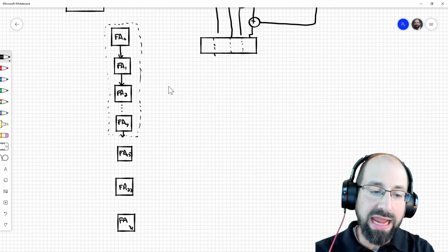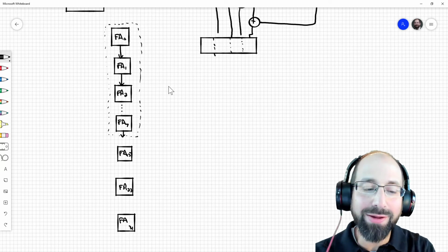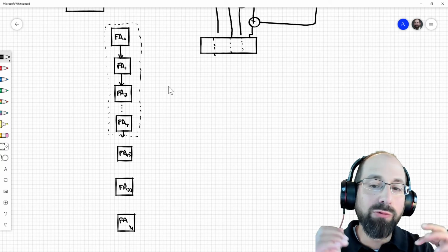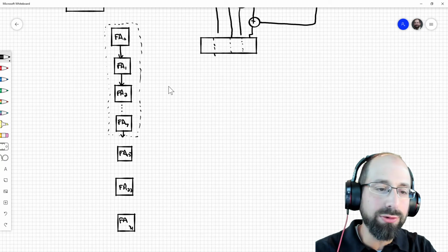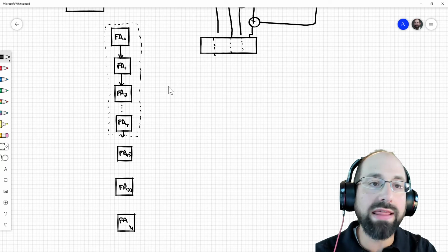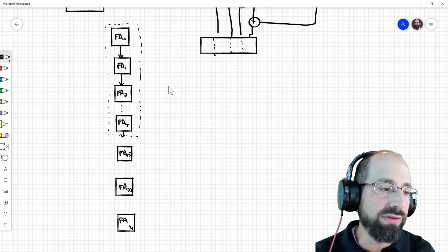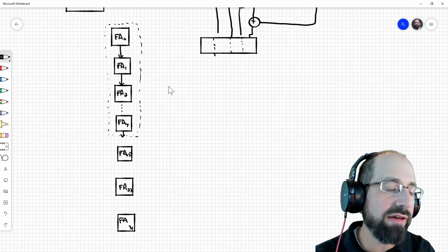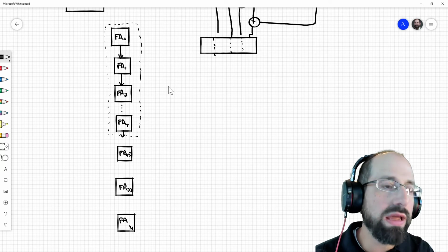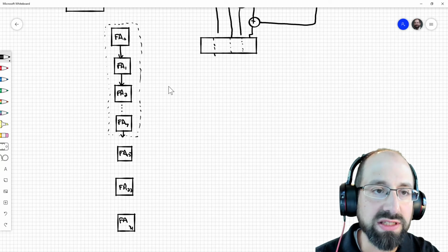If we're doing the 8-bit additions completely independently from each other, we may still have a carry out bit. Adding a mux is always the right answer, thank you. What we do with that will depend on what the instruction is specifying. But we do know that that byte of addition should be independent of the next byte of addition. That carry out from FA7 should have no impact on the carry in for FA8. So in this case, you could add a mux. The other component that would work for our purposes would be an AND gate here.